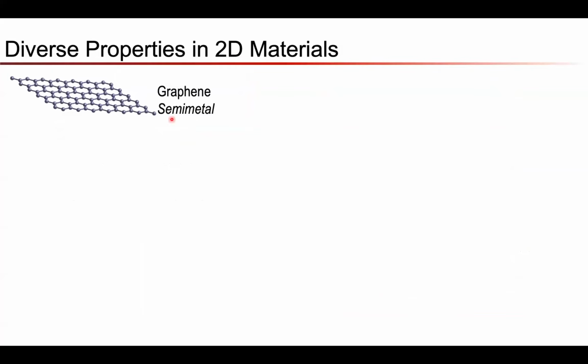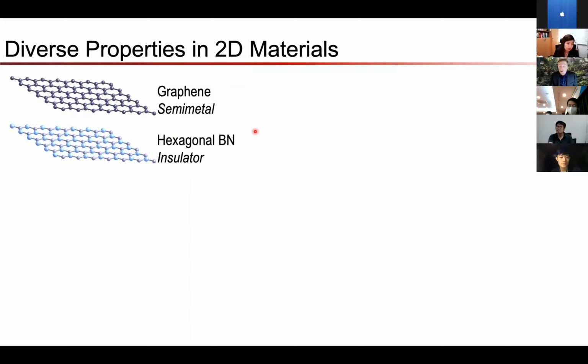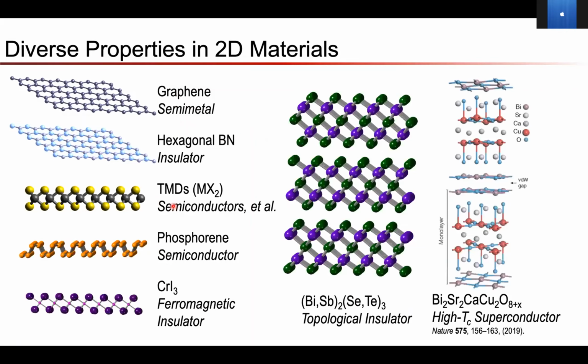characteristics. Of course, this all started with graphene, an extremely strong semi-metal that has very high charge carrier mobilities, and hexagonal boron nitride, a very low disorder dielectric, and the transition metal dichalcogenides, a number of exceptional semiconductors. But there's a wider family of two-dimensional materials out there, and they all have their unique attributes, many of which are very exotic and interesting and may enable fundamentally new directions for future electronics, as well as some really cool fundamental physics.